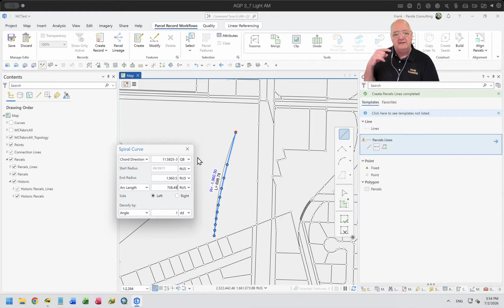When you create a spiral inside ArcGIS Pro, it's creating a graphic using a polyline. It basically is creating segments on here, but it's one single line. And you tell it how often you want to do this, whether it's an angle or a length of every 100 feet. You wanted to put a vertex on here or a bend in that curve.